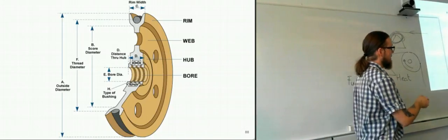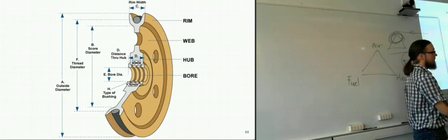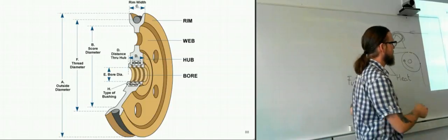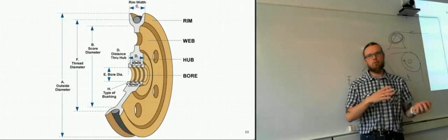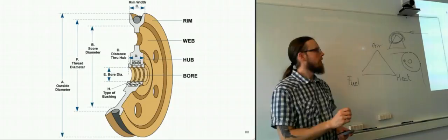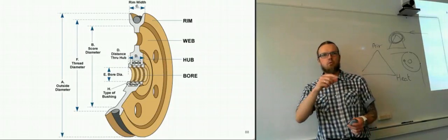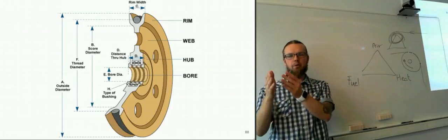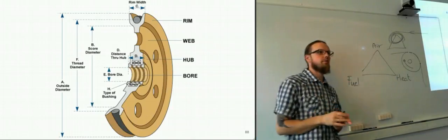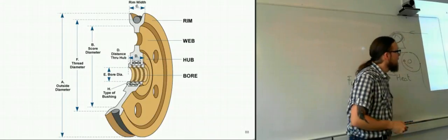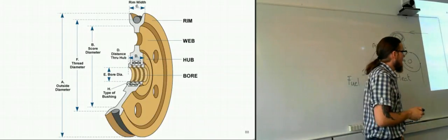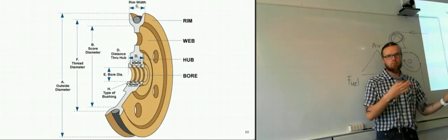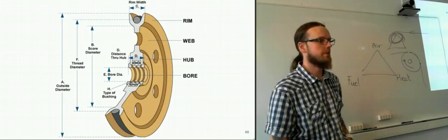So you really do need to have a sheave that fits the exact kind of wire that you're going to use. But of course the sheaves usually have a range, so maybe wires from 16 millimeters to 22 millimeters will fit in this sheave. But if you have a 23 millimeter wire, you should use the next size of sheave. And of course you have different bore diameters for what kind of axle size, shaft size you're using.